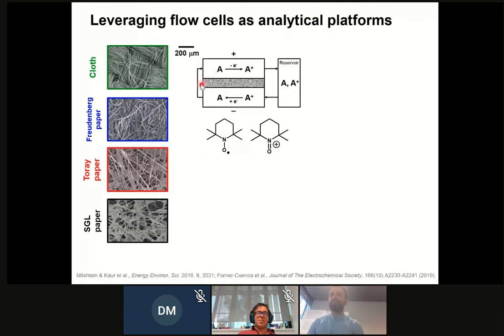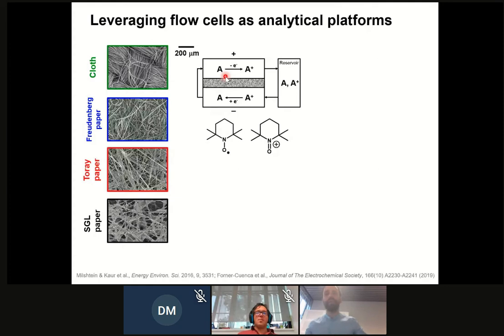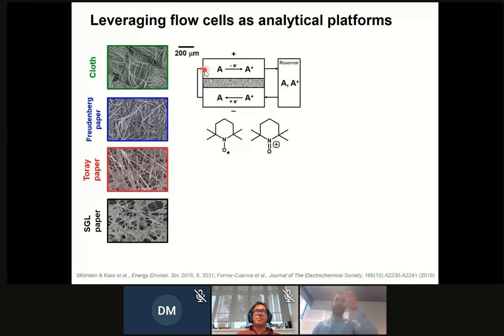So with this cell, what we do is we have a very well-controlled state of charge, and we are basically having the same electrolyte on both the cathode and the anode. By doing so, we can actually make systematic comparison of materials. It's much more difficult, however, if you would compare an anolyte with certain vanadium species with a catholyte with other vanadium species, because each half cell will have their own kinetic constants, their own physical chemical properties, and so the analysis is very confounded.